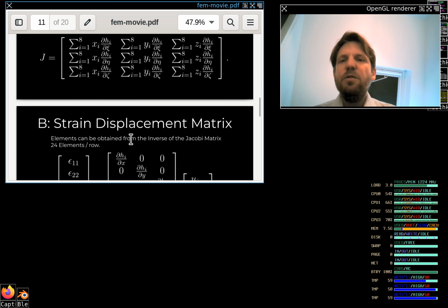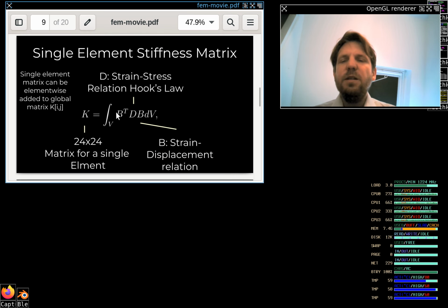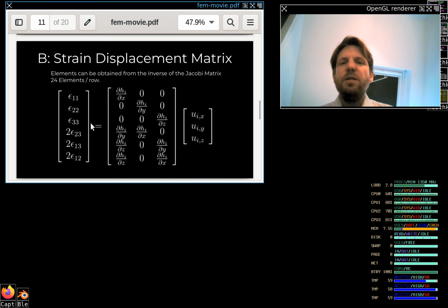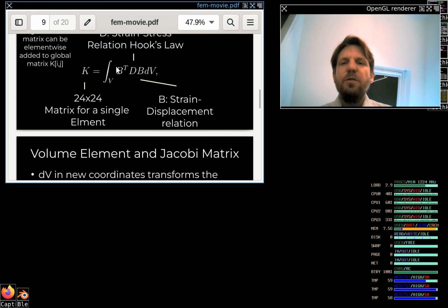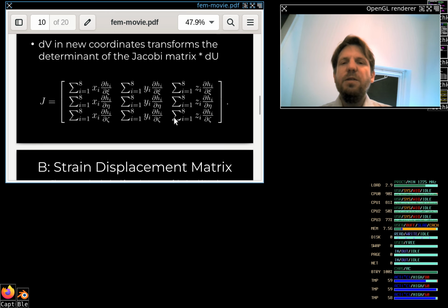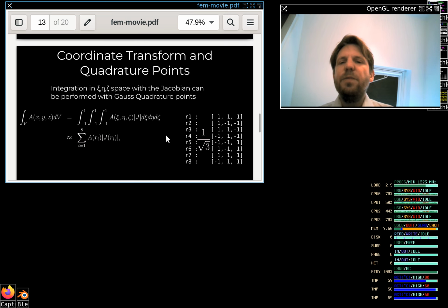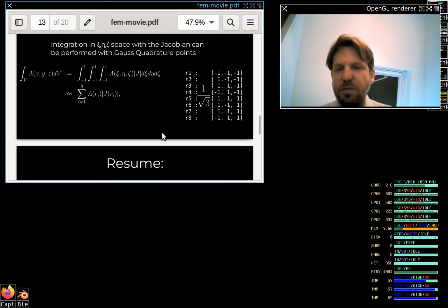And this way you can calculate your K relation, because I've just shown you that you plug in these 3 matrices and do this integration, of course. So you plug in the sum over these 8 points, and you get your K matrix out of it. That's all that there is. Because of course this is then described dependent on xi, eta, zeta, as you well know. That's the way it is.